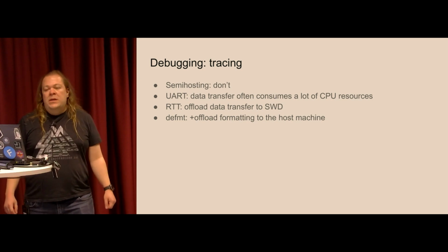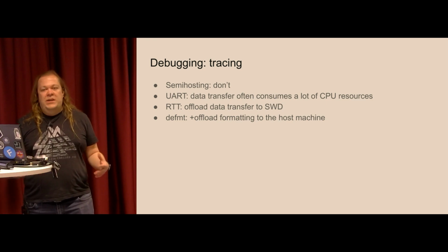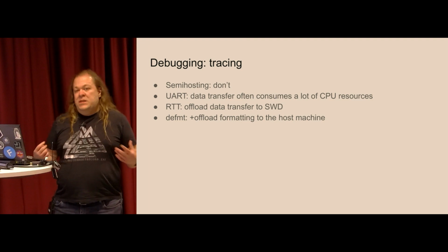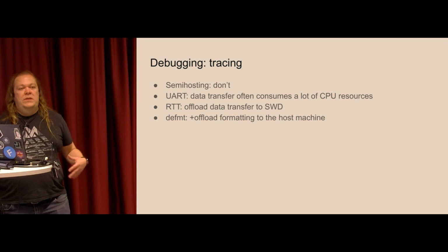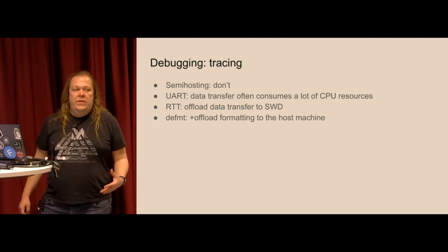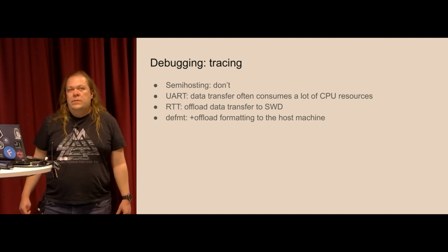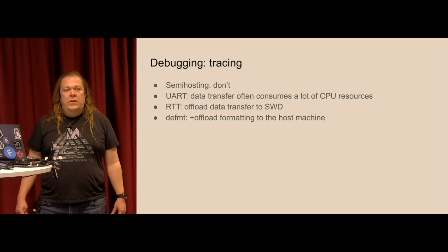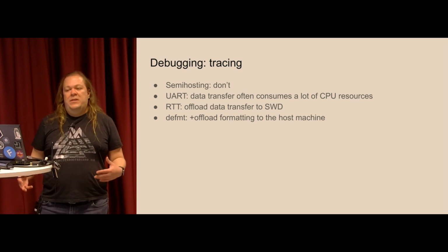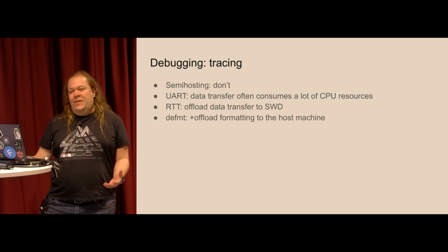There are choices. But the most important thing is that it doesn't wait until the whole package is transmitted to the outside world. Instead, you connect your debugger to the chip, and this debugger polls your memory, polls your ring buffer for this data, and grabs when there is something new in this ring buffer. So this is really cheap, especially when your chip supports reading memory without stopping the core. This is the main way you can use it efficiently, actually, because if you stop the code for each transaction, then what is the difference?